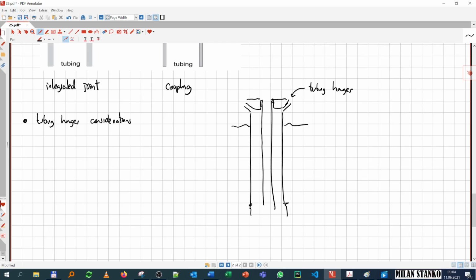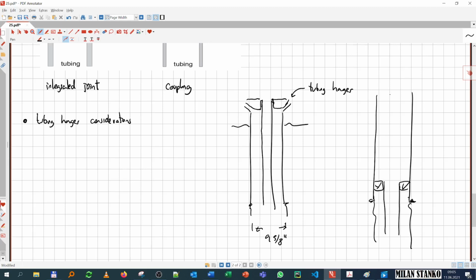So first, the production casing. Usually these diameters, so this is 9 and 5/8 inch. So you should usually fit that. And sometimes you have a liner inside. There are some cases where, for example, here you have a liner which is of smaller size. So maybe you want your tubing to go inside. Not very common, but it might be a case. So always be careful that if you're going to put your tubing string inside another string, then of course it has to be smaller than that string.